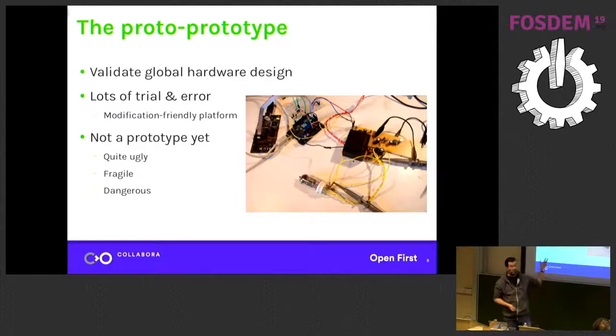In that case, it was about choosing the right operational amplifiers, because I really had to use JFET input amplifiers, and most of the time, due to offset problems, I didn't get the right results, so it really helped me select the right component for my final project.